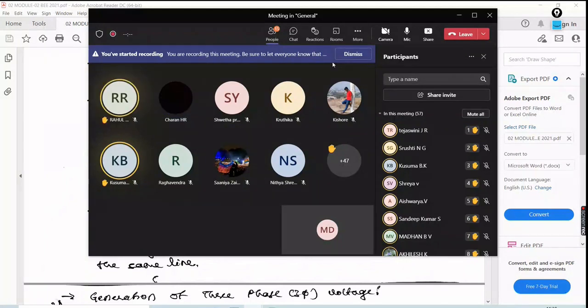Not possible, because it will compulsorily require the phase displacement. For the three-phase induction motor, I will explain the working principle, and at that moment I will recall this single-phase motor concept. No need to worry. We want the phase displacement to be caused by the single-phase power supply, which is why we proceed with the capacitor start and capacitor run induction motor. Whatever we have in our house, ceiling fan, table fan, and the single phase motor for the motor pump set, all belong to the capacitor start and capacitor run single phase induction motors.